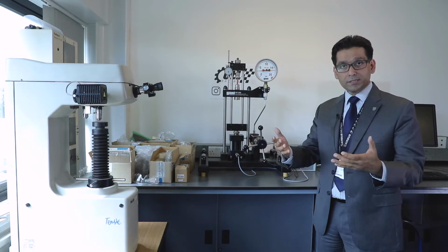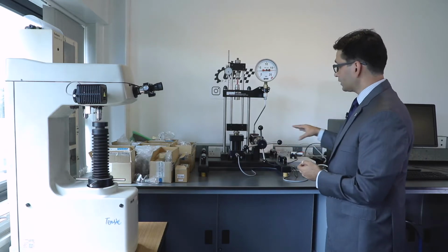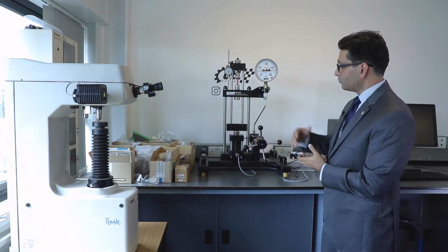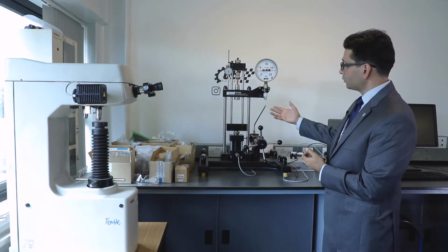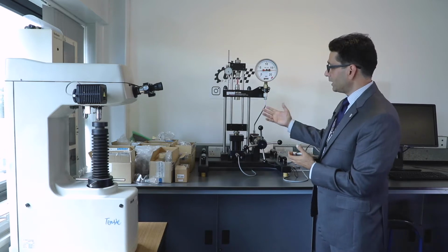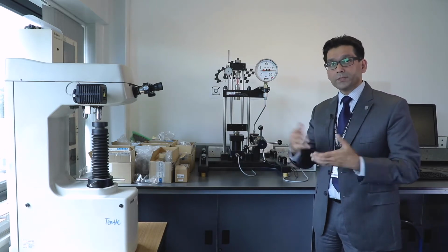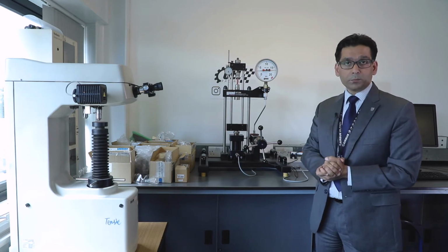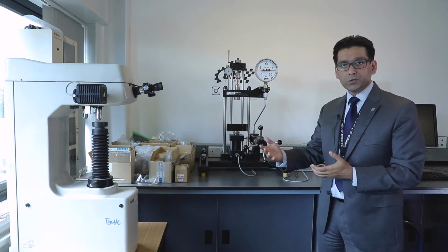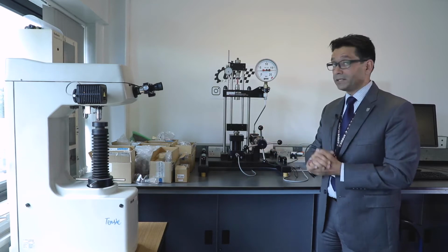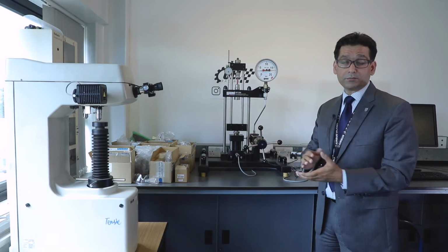They get the properties, they can actually use the computer to capture the data, or they can manually understand how the way it's calculating and how the forces are generating strain, and ultimately they can do manual calculation using this machine. Obviously, we get the key material properties like elastic modulus, ductility, brittleness, and the area under the curve to analyze the toughness of the material.